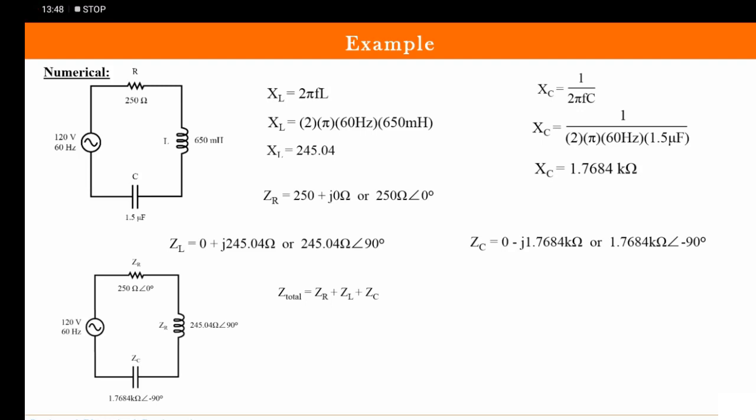So we have to find collective impedance. That is going to be the algebraic sum, so we just have to add these things. All the real parts will be added together and all the imaginary parts will be added together. Now please pay attention that in case of capacitor we have put the minus sign. So when I said imaginary parts are going to be added, it means that the minus sign has to be taken into account.